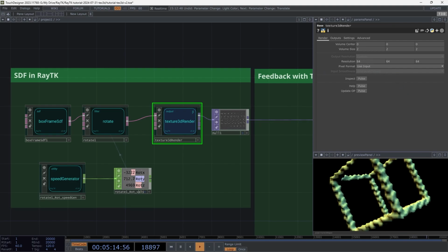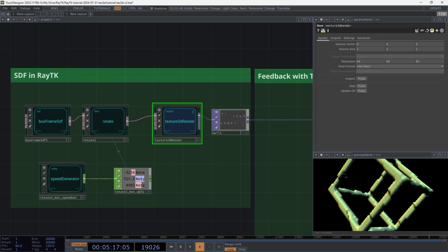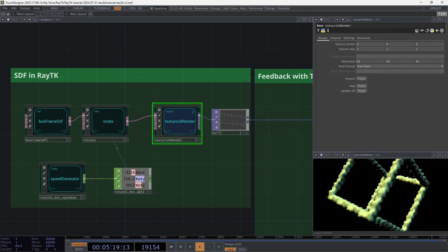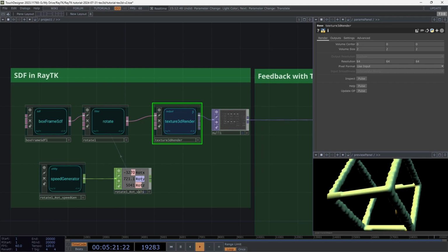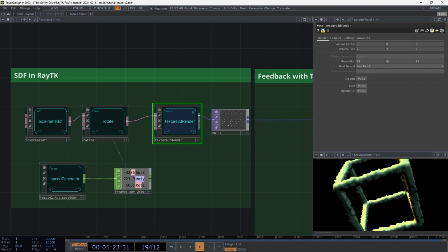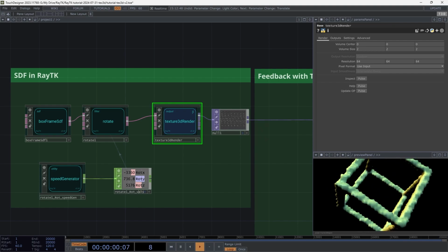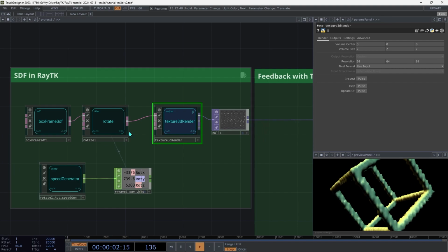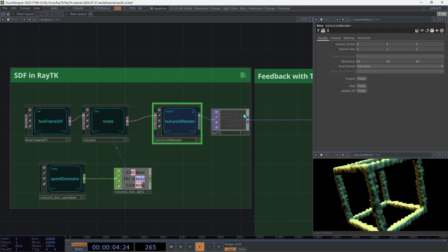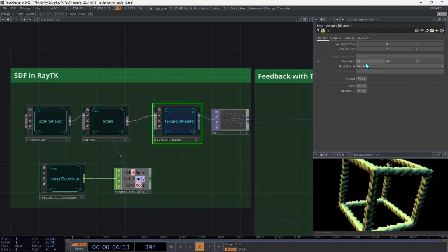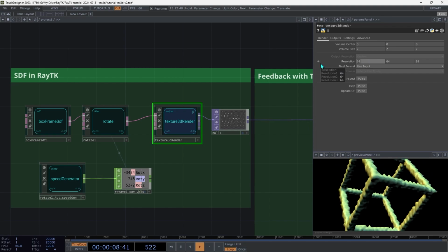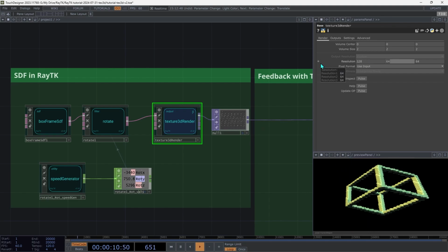And when GPU memory gets too low, you can get some kind of weird graphics problems, including issues that show up in other programs that are not TouchDesigner and all kinds of weirdness. So when you're increasing it, start with small increases until things look decent, but leave it as low as you can with it still looking okay. So I'm going to go up to maybe like 128.